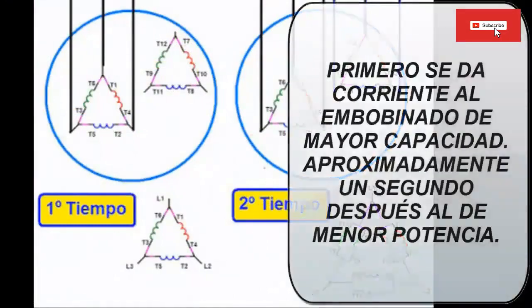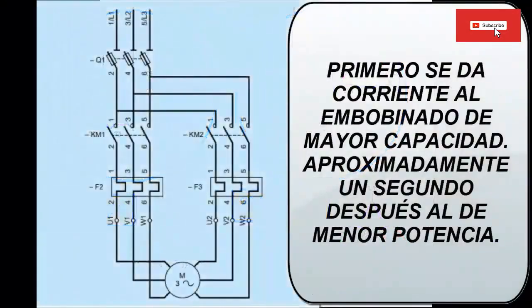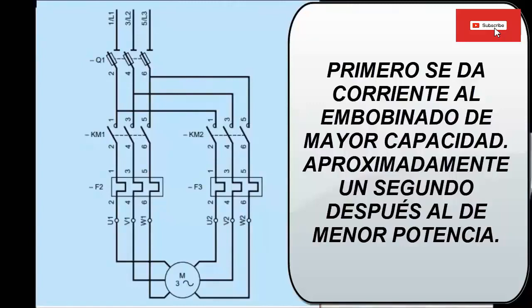During starting, a single motor half is directly coupled at full voltage to the mains, which splits both starting current and torque. However, the torque is higher than what would be provided by the star-delta starter of a single-winding motor of equal power. At the end of the start, the second winding is coupled to the network. At this time, the current peak is weak and short-lived, since the motor has not been separated from the mains.